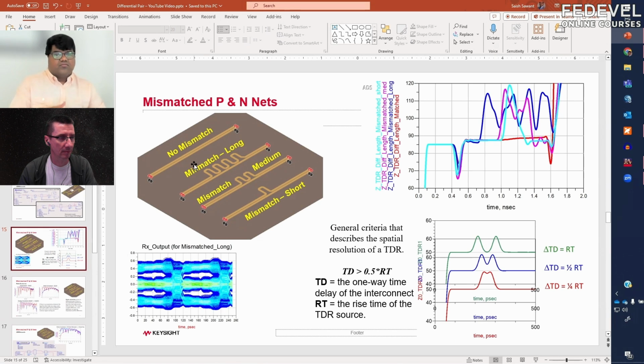So when you're doing this, we're talking about differential pairs, so we really get biased towards viewing the TDR response, and we want to ensure what our impedance profile is, right? That's the very first thing that any typical user will do. They will do an EM extraction and plot this response, and they will see the red curve is the length matched. You'll see that there is a port here and a port on the other end, and then it's going to an open. So it's a clean, flat 87 ohm kind of a resistor.